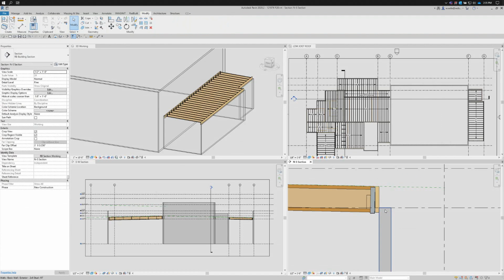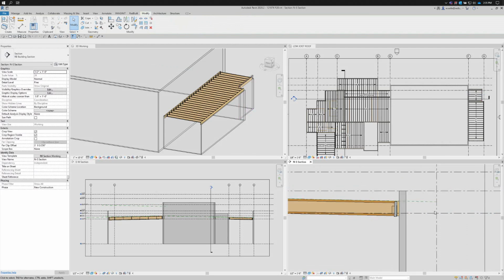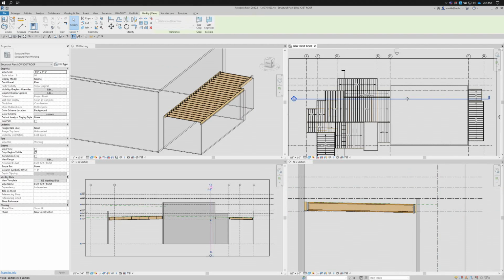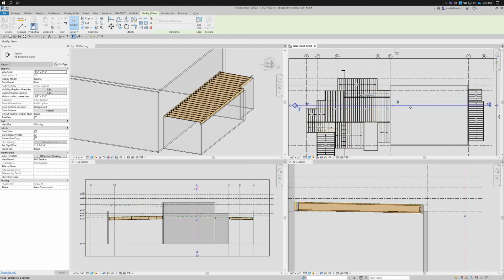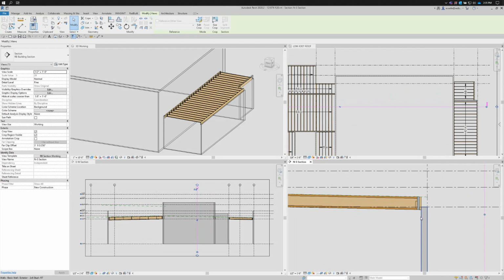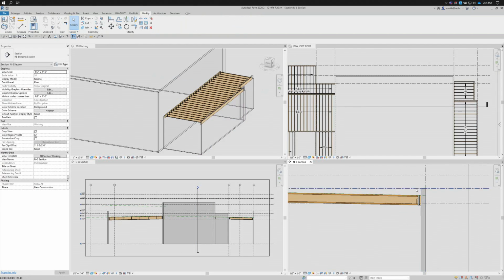There, now it's close. Now this wall has a bit of a parapet, and we can simply take this and stretch it up, kind of clean up the view. Now next we can pull down and look at the other wall, and we have a similar condition with this exterior wall, and we'll drag this up to the low parapet.